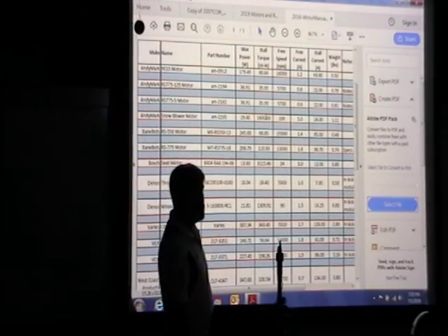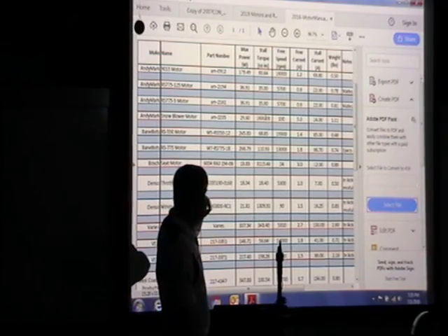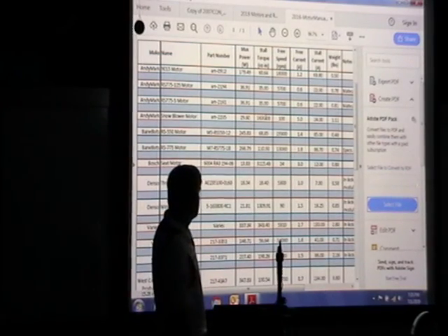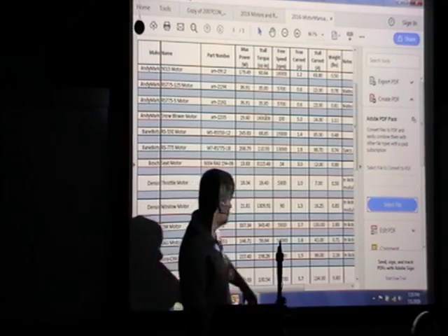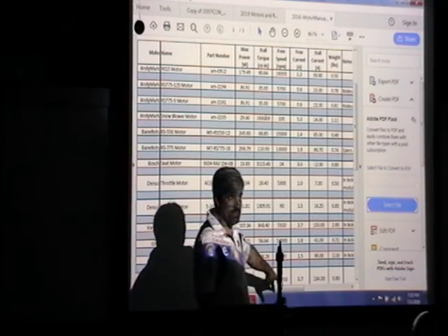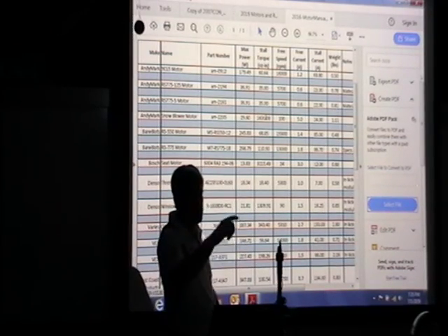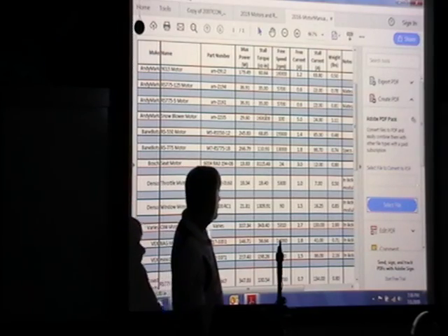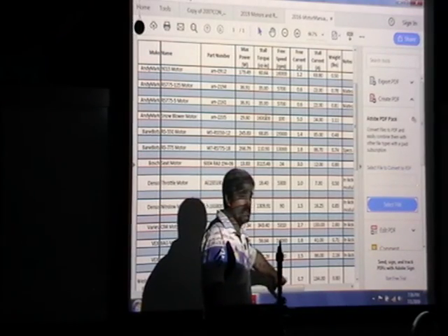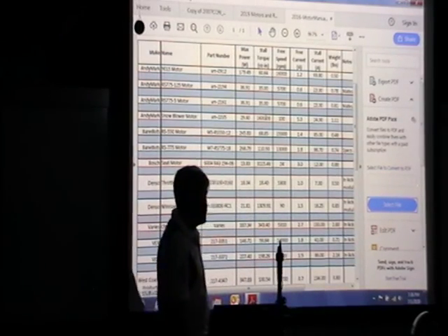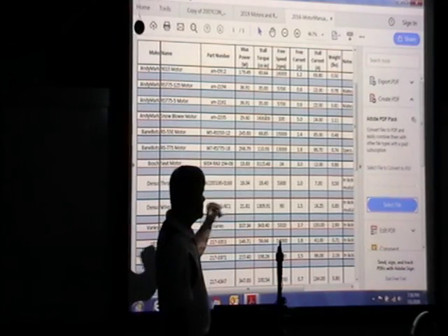So there's opportunity here for a lot more RPM than some of you kids are putting in your designs. Now, is there a lot of torque out here? Probably not. Remember that power curve tapers off at the end, right? But there is opportunity. You're not going to get max power at 100 RPM either. So you're going to put a fairly decent reducer on that.